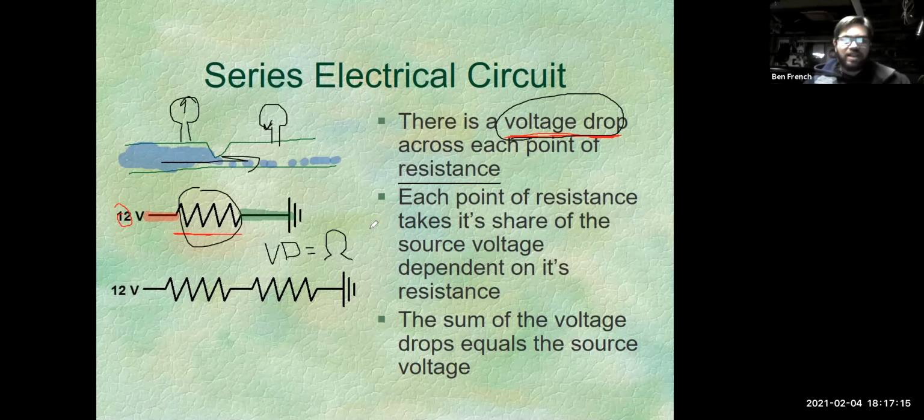That component in that picture, that could be a rear window defroster, because it's basically a big resistor grid. As the current flows through it, it gets hot, and that's what takes that fog off of your rear window. And if you've ever turned on your rear window defogger, you'll notice that it bogs down your car quite a bit, because it does take quite a bit of current through that big resistive element on your back window to make heat and defog that rear window.